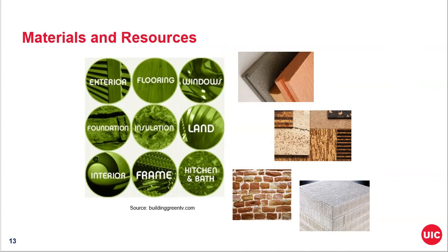The other best practices include, be careful with this one, considering structural materials that do not require application of finish layers, using materials with a high recycled content when possible, and using materials that are sourced and manufactured locally. This is very important because I'm going to go back to this one later. Also extending the life cycle of existing building materials and reducing the waste generated and the environmental impact of materials. Again, everything is designed around that sustainability principle.